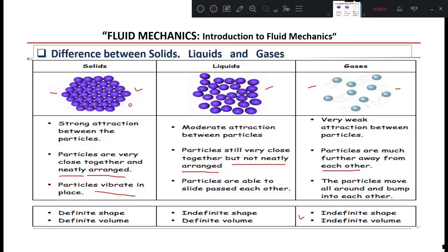And if you differentiate based on the ability to resist external forces, solids will resist all kinds of forces like tensile, compressive and shear forces. But liquids have no resistance to tension forces; they won't resist any tensile force, but support compressive force when placed in a container. Under shear, the fluid particles continuously deform. Gases have no tensile strength, but can be compressed very well.